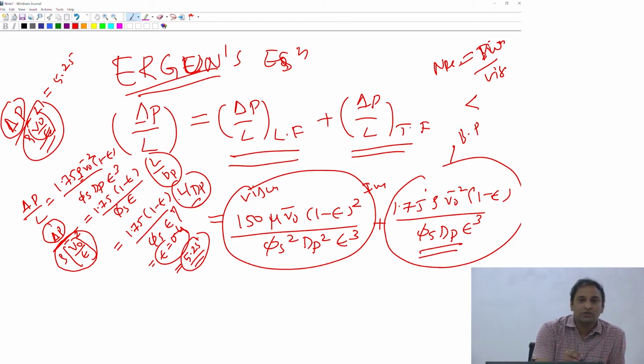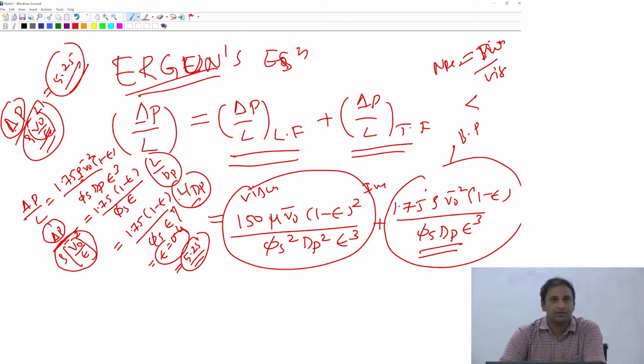If you did a similar analysis for flow through pipes, you would see this ratio is much less than 1, or 1 or less. The fact that this is a much larger number tells us that the kinetic energy losses in the packed bed, because of the change in cross-sectional area of the conduits through which the liquid flows, plus the change in direction of the fluid, lead to much higher kinetic energy losses in flow through packed beds. That is what I wanted to say.